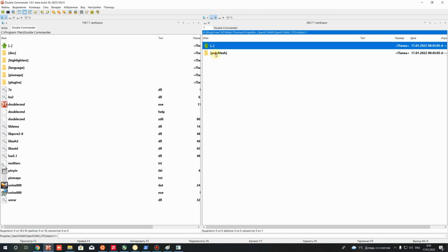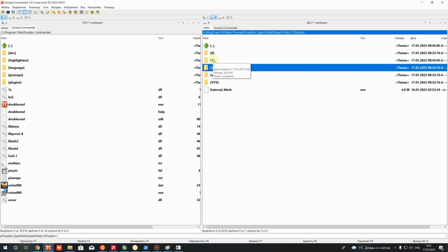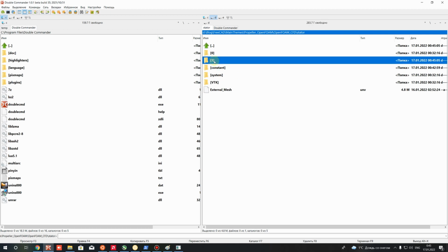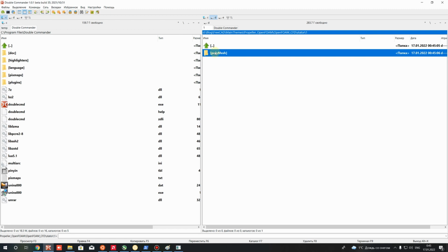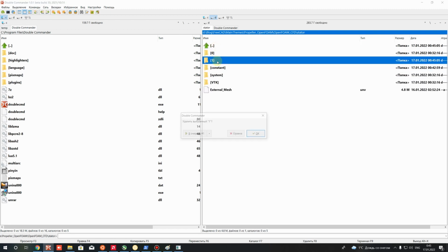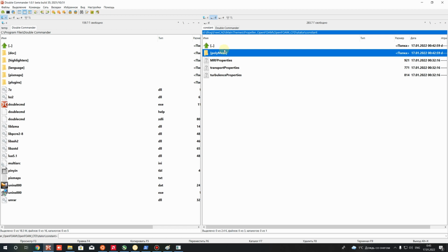And you will get here some polyMesh, but we merge these cases into one folder. We can just use this polyMesh and paste it here, but we can delete this, and I will show you another way how you can automatically merge the meshes and save it, overwriting it to the constant folder